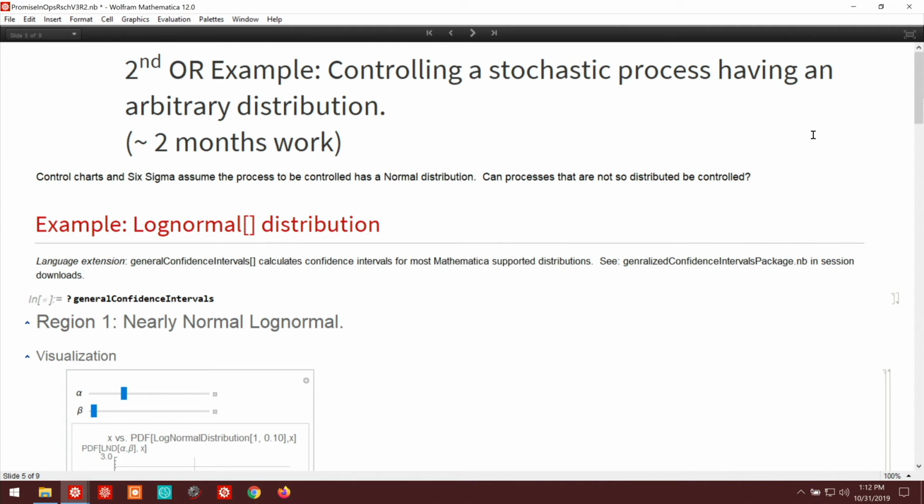And in practice, if you change every time there's something that isn't accepted by quality control, then you end up with what's called chasing the mean, and you can end up almost anywhere if you do that. It's a good way to get into trouble. The problem is largely solved for the case of the normal distribution. One typically uses a chart with a limit and then looks for patterns on excesses of the limit. Okay, but there's very little in terms of non-normal distribution.